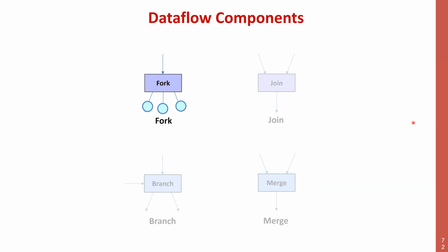It means that basically it has this handshaking with the predecessor and then repeats this handshaking with multiple users. Join is the dual, is the synchronizer that is dual to this, which waits for all tokens to arrive at its input and then lets them pass. It's essentially the same component that you imagine at the beginning of the adder that I described before, where the addition is done by joining, by waiting for both of the operands before we start.